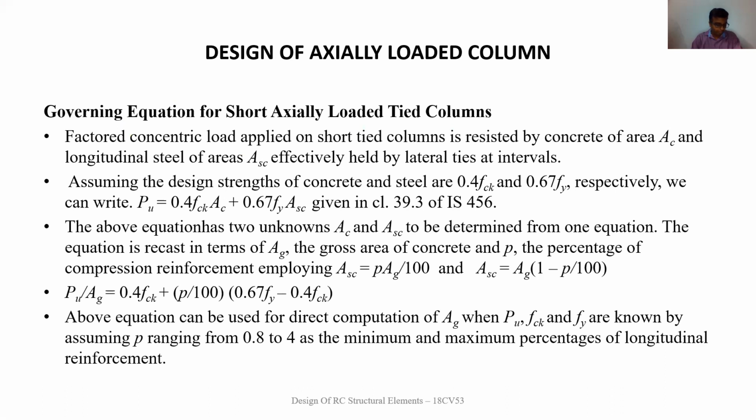The maximum design stress of steel is considered as 0.87 times fy, where fy is the yield strength of the reinforcement.